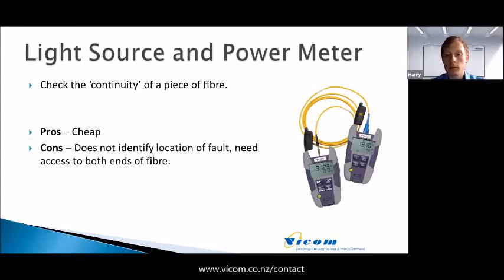Remembering, there are a couple of things you need to remember here. First of all, the light source and power meter is not going to tell you if there's a fault. You as the tradesman or technician need to interpret the results given by the power meter, and then determine if that's a serviceable link or not.